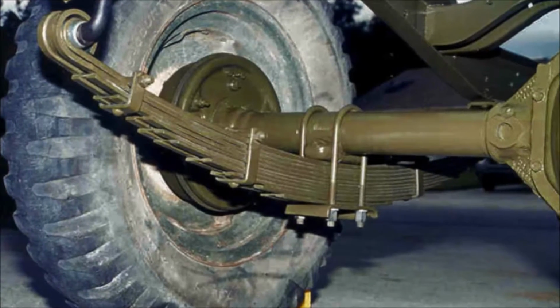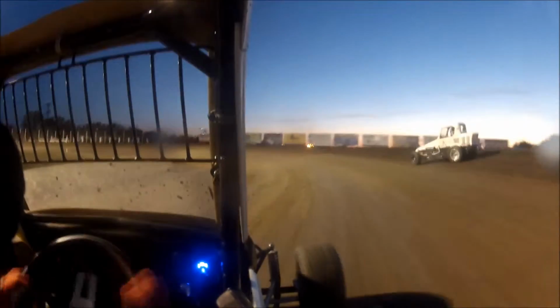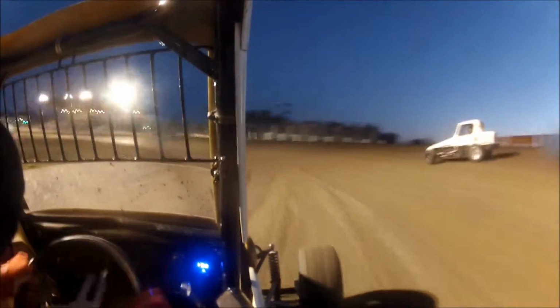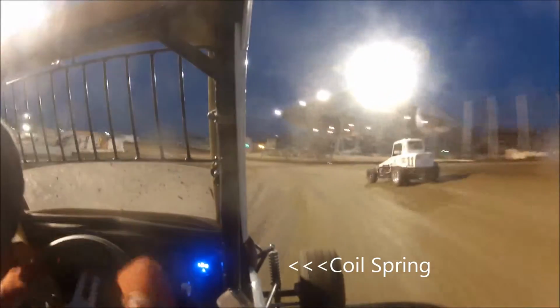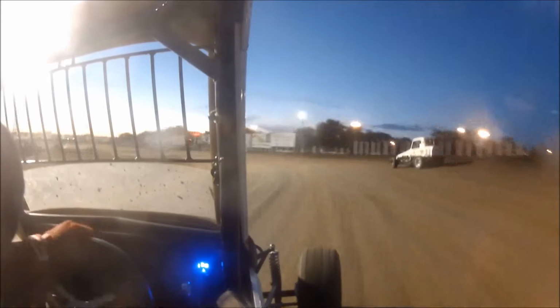In a leaf spring, the amount of leaves control the stiffness. How they are held in place will determine their endurance. The most common type of spring, and our test subject, is the coil spring. The coiled wire twists during the spring's compression and extension cycles. As you can see, they take up a small amount of space, which is a great advantage.